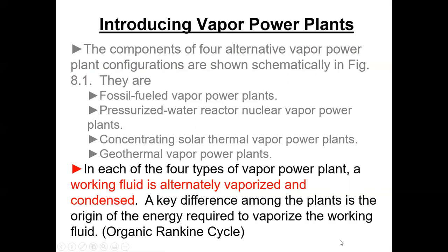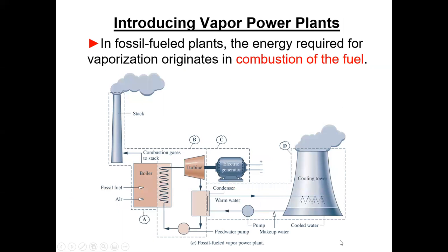And so if you use waste heat from an industrial process, you can run that flow of hot gas over a heat exchanger, and that heat exchanger can cause this organic fluid to boil at a much lower temperature than you can vaporize water. And so the basic components of the cycle are the same. It's just that the working fluid can be selected to match the temperature of the waste heat that you're trying to recover. So that's kind of what an organic Rankine cycle is all about.